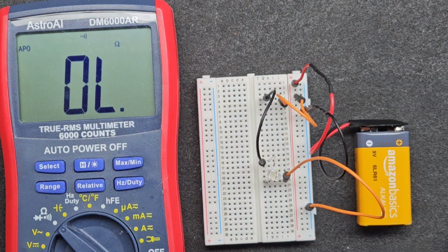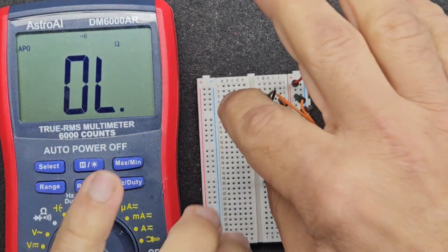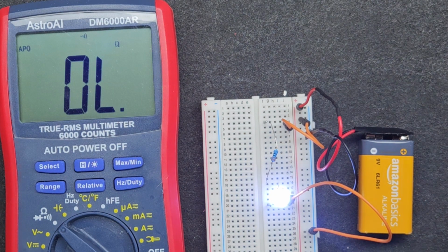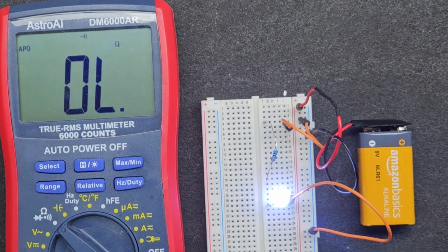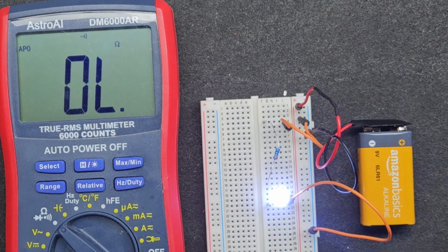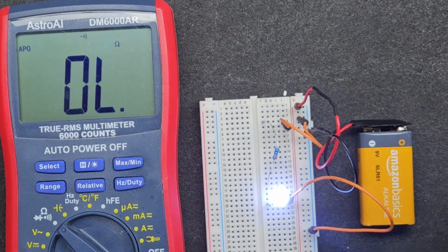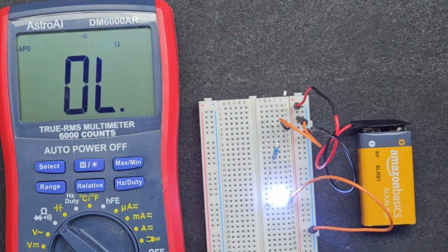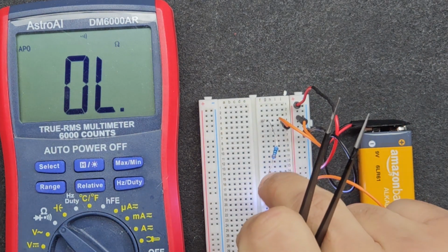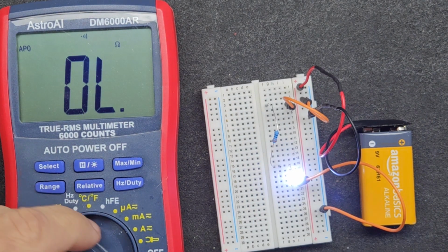Back to the whiteboard. Let me show you one more thing. So what's happening here is we have a 9 volt battery, of which the LED is taking up 3 volts. Therefore, the resistor must be consuming 6 of the volts. So the 9 volts comes in, the resistor takes up 6 of it. The LED takes up 3 of it. And back to 0 voltage, right? So that's how it happens. So let's just take a look here.